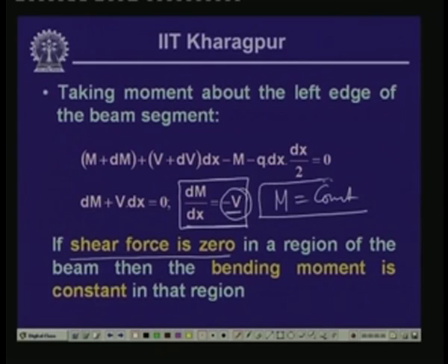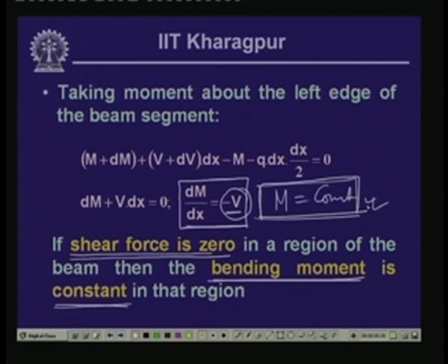So, the portion in a beam where the shear force is 0, the bending moment at that portion will be constant. This is an important observation, and it will be helpful when we will be drawing the shear force and the bending moment diagram.